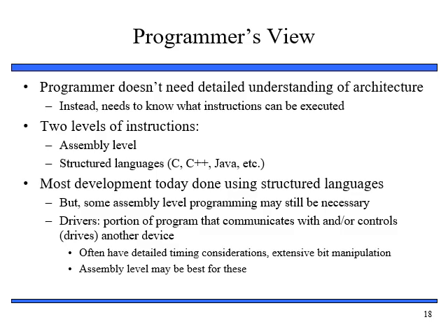Most development today is done using structured languages because they are easy to write and easy to understand, and you do not require low level understanding of the instruction. But some assembly language programming may still be necessary, so the programmer needs to understand the low level language up to some extent. He or she needs to understand what is a jump instruction, what is a move instruction, what is a load instruction, what is a store instruction. Commonly used instructions like that must be understood.